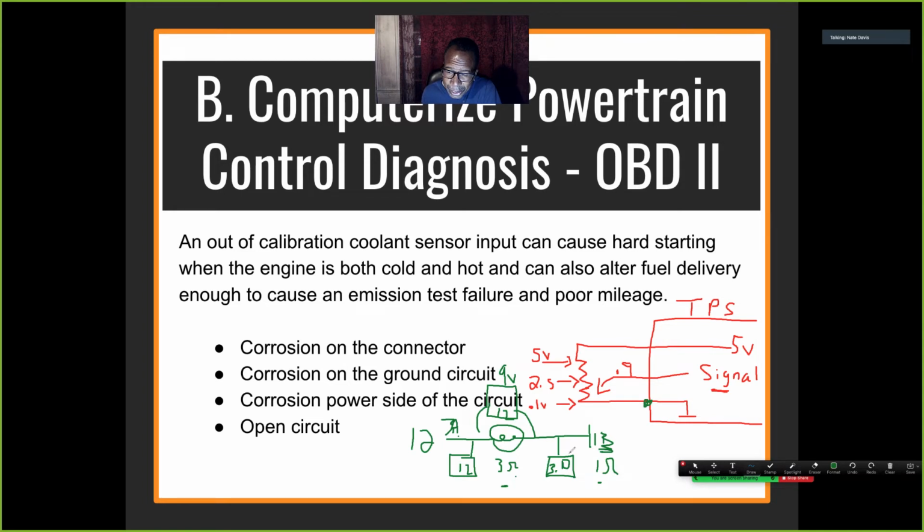Because all of a sudden now, my ground circuit voltage just went up. I'm doing a voltage drop right here and it went up. And remember, this is a voltage drop here, and this went up because of resistance in this circuit. So if I got resistance in this circuit on the ground side, just like on this side, my voltage drop also should go up here to push the current through the resistor down line, through any unwanted resistance down line.